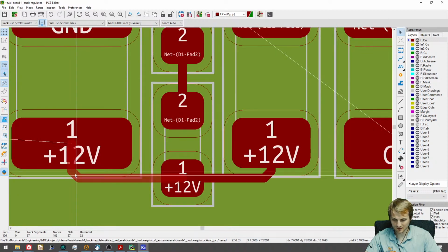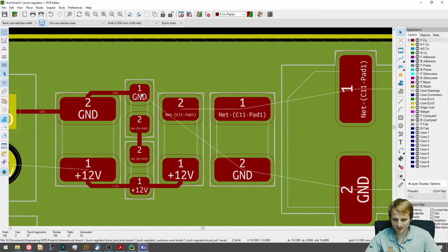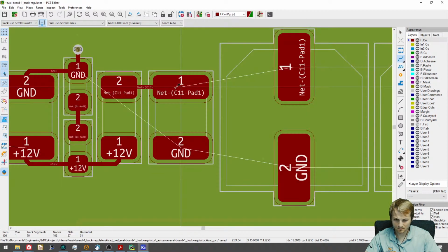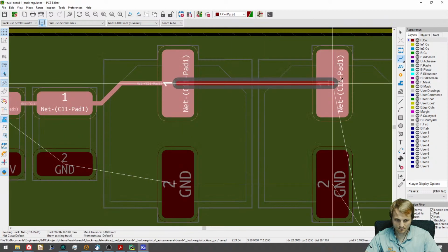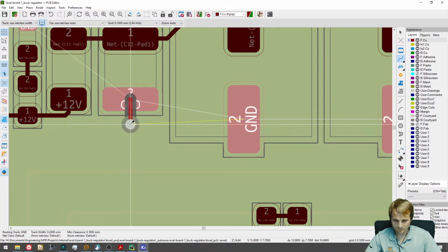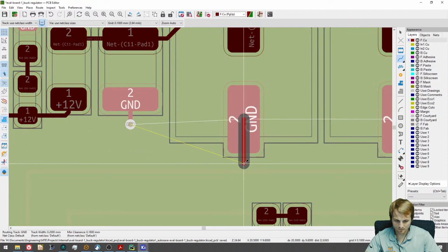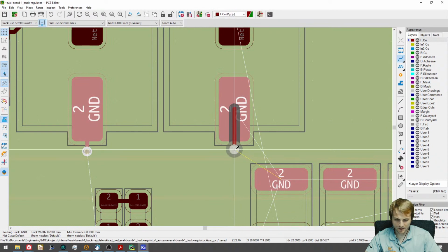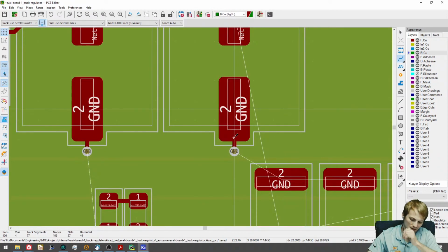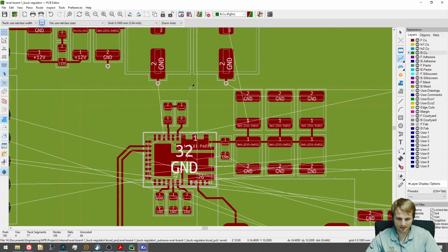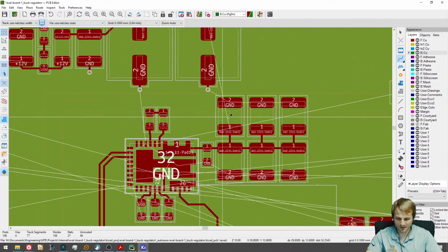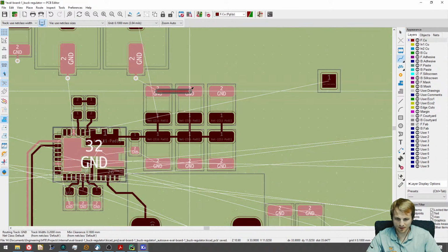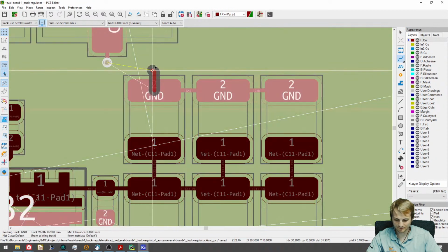But for now, that takes up way too much time. And I like not putting the copper pour on the top layer at the start, because then it lets you see where all of the grounds are connected without them just connecting on that top layer, which is super helpful as like a double check.